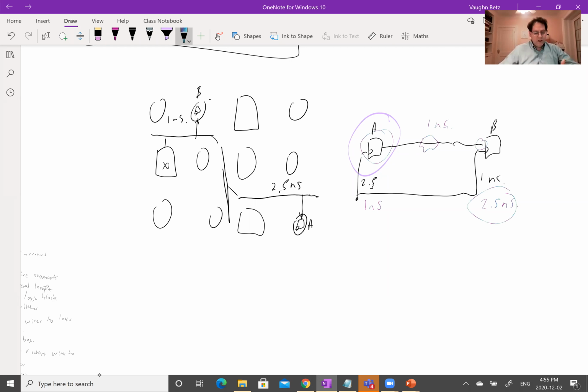That's also bad. So skew hurts me either way, right? Whether it's skew where my launching register is launching late, that hurts my clock period, or if it's skew where my launching register is launching early, that exposes me to hold time violations. So I don't really like skew. And a regular routing algorithm with regular segmented routing, the kind we have in an island style FPGA, is going to produce high skew routes. So I've shown here a net with just 2 sinks, but many people highlighted the fact that clocks tend to be high fan out. So if I make this 10,000 or 100,000 sinks, this starts getting really complicated. It's got branches all over the place to many, many registers, and the delays to those different registers are not very similar. So I'm going to get skew.